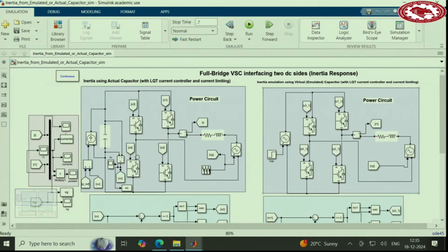So here you see there is a capacitor on the left side of the converter. Here there is no capacitor. It's just a battery, a voltage supply. And this capacitor obviously needs power, right? The power should come. But we don't have a power source in Simulink and in other simulation software. But we have a current source. So you can put a current source here and then adjust the amount of current properly such that the amount of power that you want is coming here.